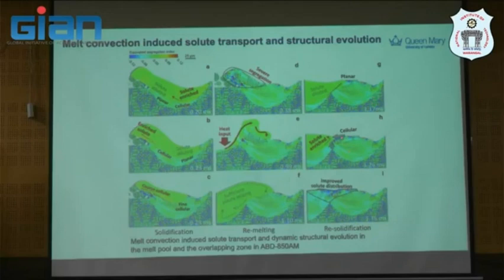And the cellular structure actually becomes penetrated here. This makes this one enriched. So you will see that enrichment of the solute is related to cellular growth here. And then you get an improved solute distribution. That means if you print more and more, the solute will, but still, in some cases, without care, you will trap some solute, and that's what we call solute trapping.